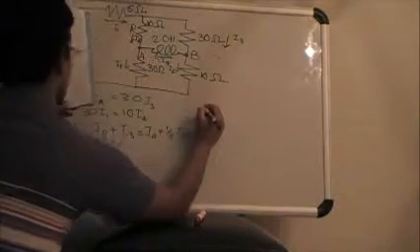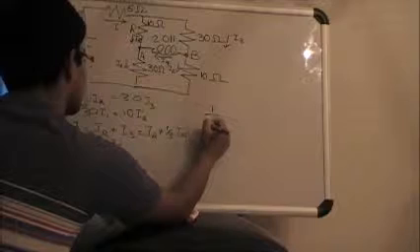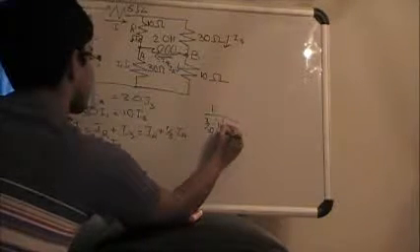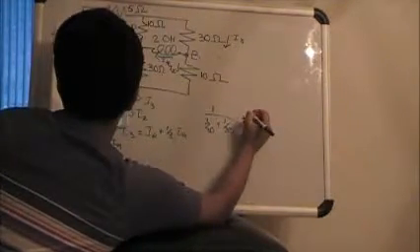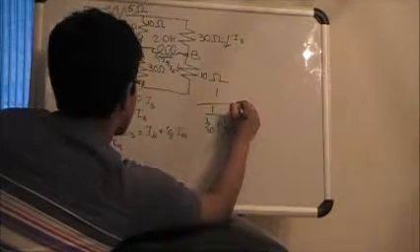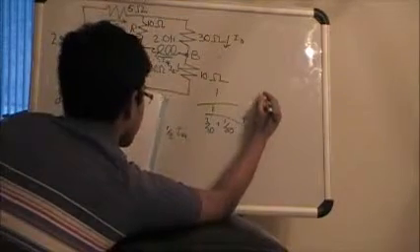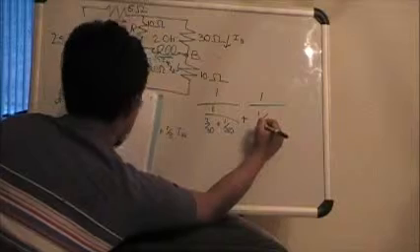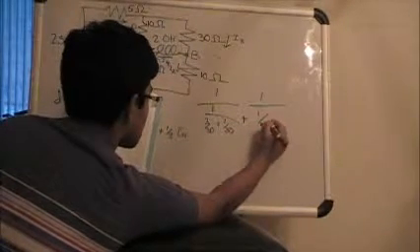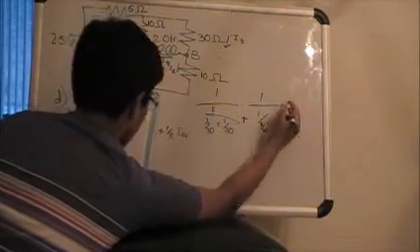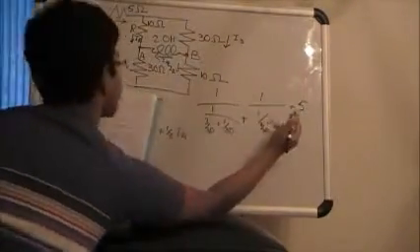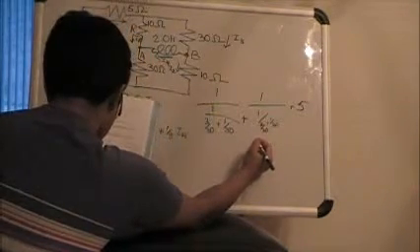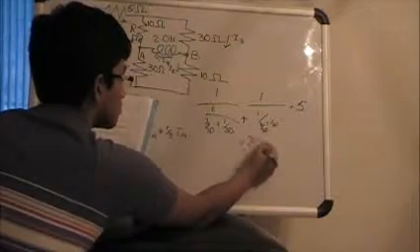So to find the equivalent resistance, you do 1/3/30 plus 1/30, so that this is 3/30 instead of 1/10, just because I made it the same denominator, and plus 1 over this, because that is what the equivalent resistance is, and then plus 1/1/3/30 plus 1/30 plus 5, because that's going to be in series with this part, which equals 20 ohms.